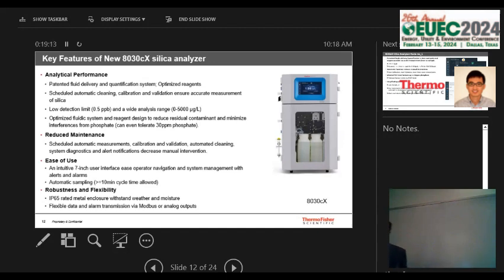You can set calibration at an interval, and validation at an interval. Calibration means, this month I calibrate at this day and this time, and validation is, I want to make sure my calibration is still good, right? So I can validate every 3 days, every week, whatever you want. And that tells you, maybe 3 weeks or a month later, my calibration drifted and I need to recalibrate. You can look at the validation log and say, during this period of time my data is drifting off by 1 ppb, and then you can correct for that too.